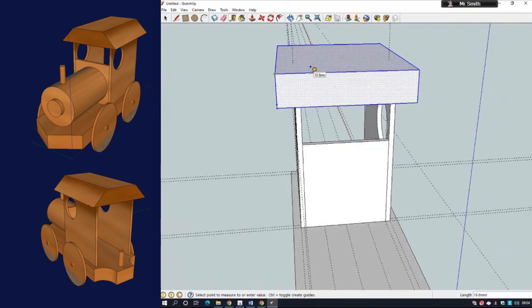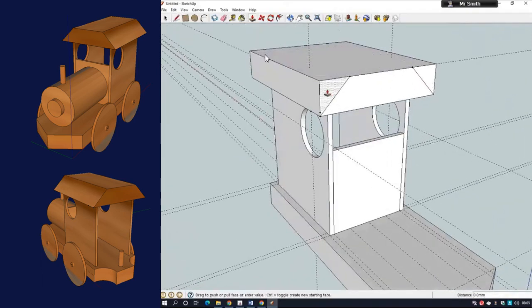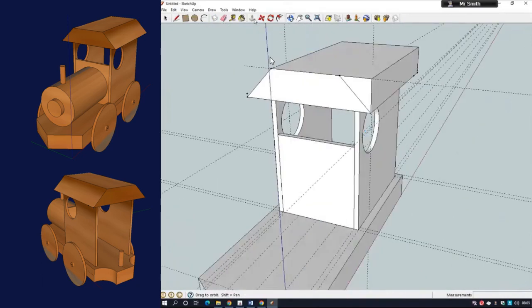And the next thing is I'm going to use a chamfer, which means it's like a little angle on the roof so that the water would come off easier. So I'm going to click off that, select just into space and deselect. Drag along, type in 18 millimeters because that's 18 thick. Go along 18 millimeters again. Just left a little dot there. Draw a little line from there to there, and from there to there. Then you can use the push pull tool to then push it all the way out. Just makes it look like more of a roof.